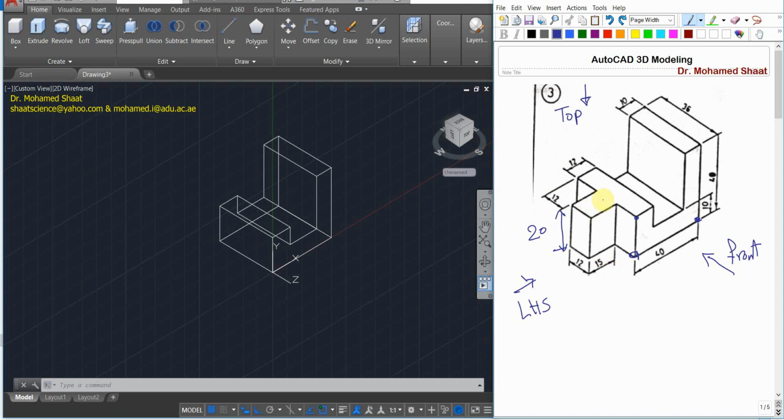For example, you can move the UCS, the coordinate system, because as you can see here in the AutoCAD side, the XY plane is already located over this face. So I can move this XY plane, for example, to this face. I have to manage the UCS, move it so the XY plane is over this face, then I'm gonna extend it back with this thickness, which is 12.